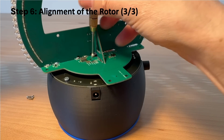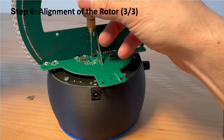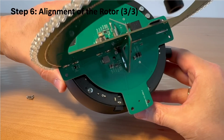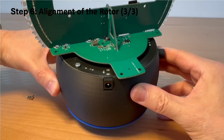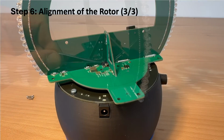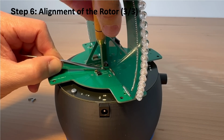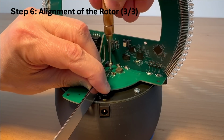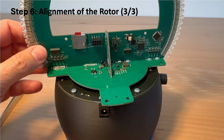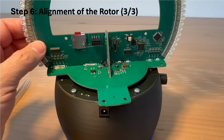To mount the LED unit, you first insert the two mounting screws. Then you carefully screw in the four adjustment screws. Using a pair of tweezers can be very helpful during this step. As you can see, all the screws are now in place.